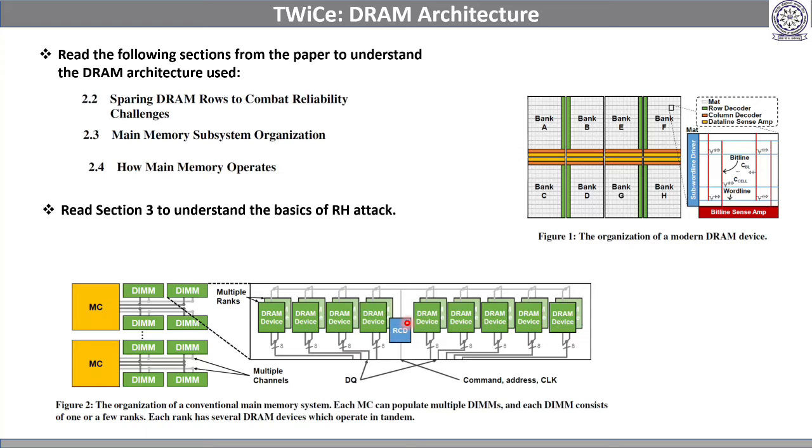A disadvantage of maintaining the counters in the memory controller instead of the RCD is that one memory controller is managing many DIMMs. In a real machine, maybe there are four slots available for a channel, but we will not insert RAM in all four slots. Assume the memory controller has four DIMM slots, but currently memory is inserted in only two DIMMs, and the other two are empty.